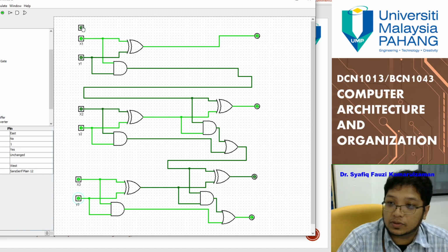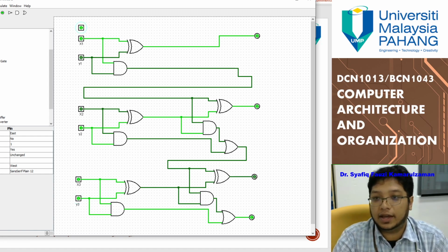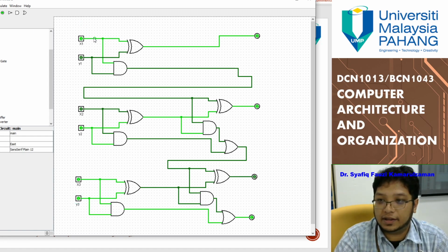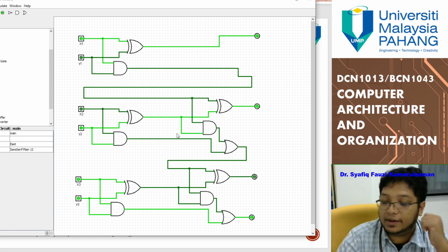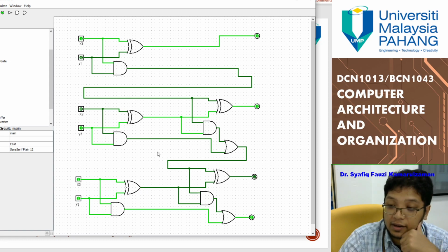For the beginning, you need to use a half adder because we don't have a carry in for the first bit. For the second bit and above, you will have a carry in for the full adder. In case your PC is up to 64 bit, you will have up to 64 adders arranged side by side to do an addition. So this involves a lot of transistors.